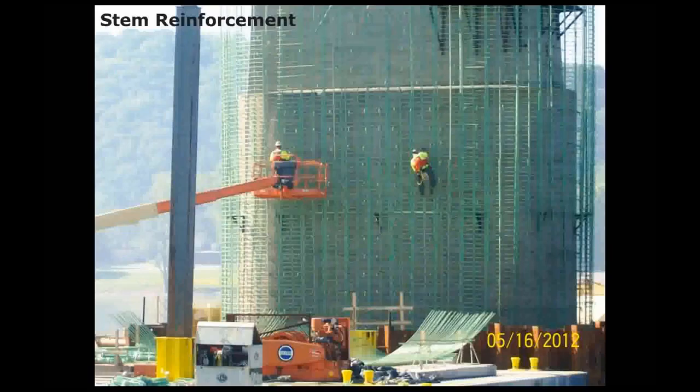And then we're constructing the new encasement rebar around the perimeter of that stem. And we're going to put the formwork up and encase all that from the top of the caisson up to the bottom of the proposed cap.